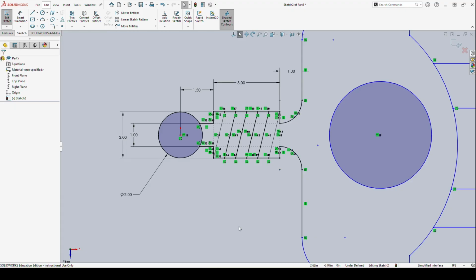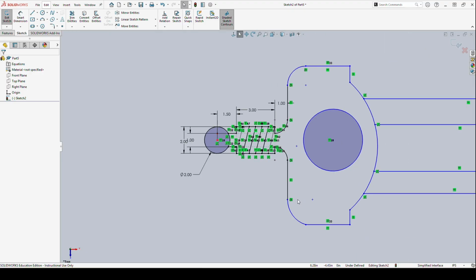I'm saying that I just defined the radius of this top one with this 1 inch dimension, and now I've added this equal sign here, showing that both this and the one below have the same radius, because we talked about how curves, when we use the equal, is defining the radius. And I've fully defined there.